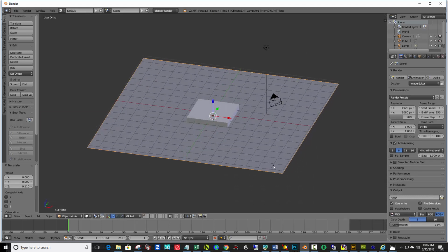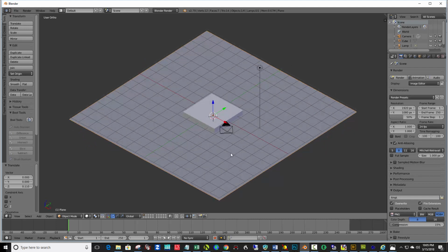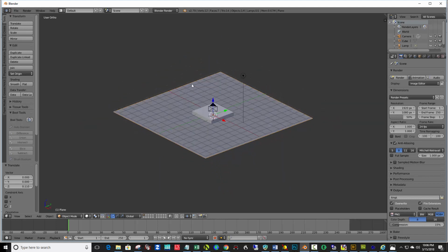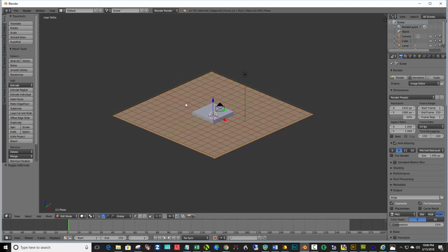Okay, now I want to get the position of the camera so that it's in front of me, I'm looking through it. And on these back 2 corners, I want to extrude them and make them taller. So tab over to Edit Mode, hit the letter A to deselect everything, choose Edge Selection down in the middle button here.